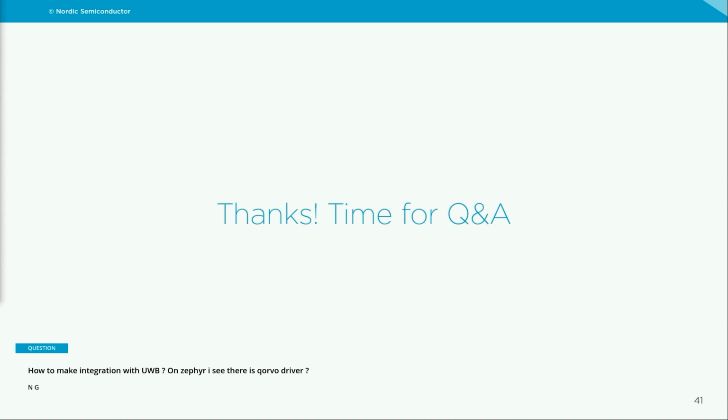The next question: is there a ready reference solution on AoD from Nordic? Yes, the samples that are in the SDK do support AoD. So you can build the samples for AoA, or you can build them for AoD; both of those options are available. But again, the limitation is, as for all of the code here, we end at the point where we deliver the IQ samples up to the application.